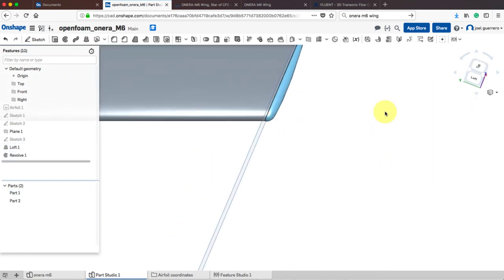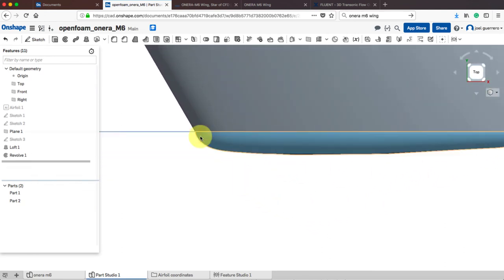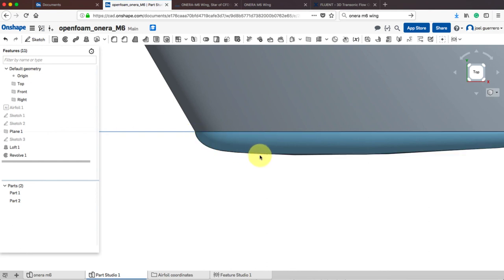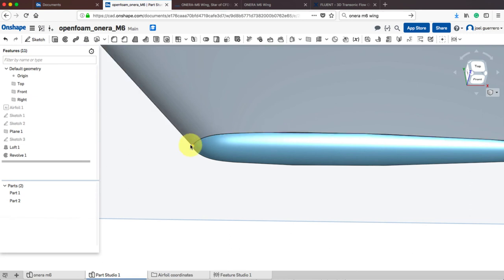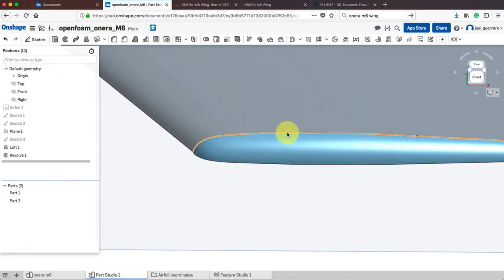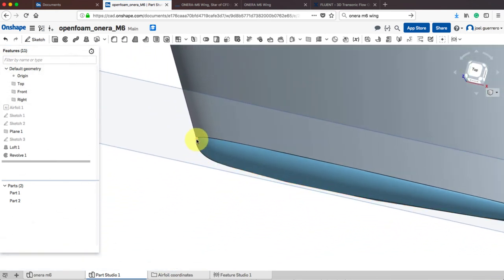click here and see that you have the tip there rounded, nice, but see that this one probably is not ideal. So what we're going to do in another video is just to create a guideline as we did with the loft. Okay, so we're going to create a center profile, then we're going to loft it until this point, and then we're going to add two guidelines, one here and the other one here. So probably this guideline here is okay, there's no problem there. We have a problem here, so we can add a guideline here just to smooth this transition there.